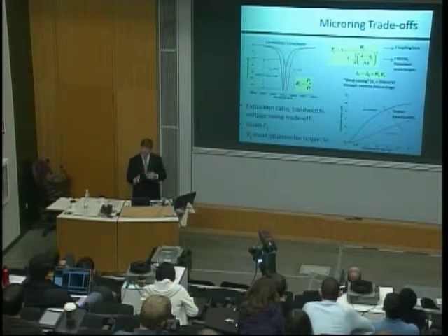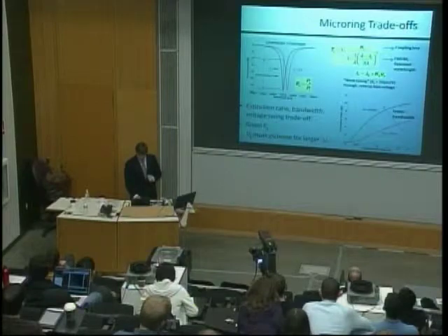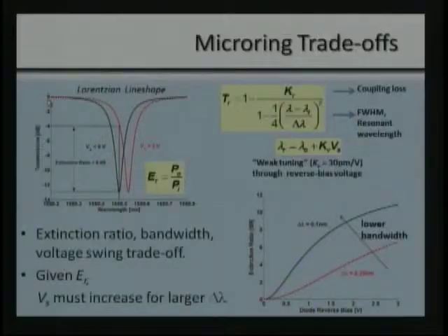So this resonance, this coupling behavior, is summarized with a Lorentzian line shape. Basically, as I said, at one frequency, light is coupled into the ring. And so the transmission across that waveguide that we described basically shows this dip where all of that one frequency jumps into the ring and is stored. When we want to modulate this Lorentzian line shape, we're going to apply a voltage across it, which shifts that Lorentzian a little bit to a new frequency.